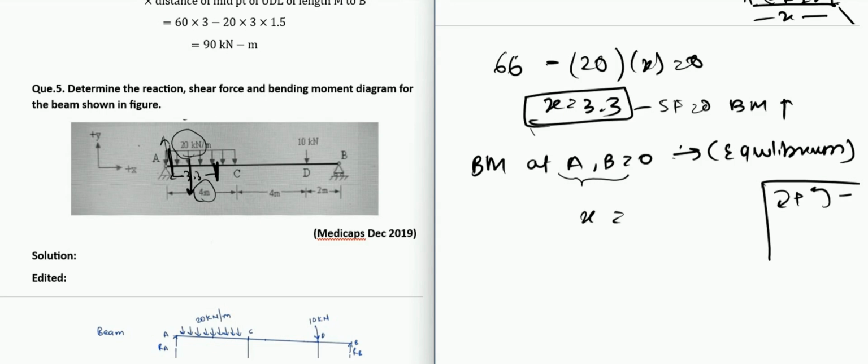And if you are calculating from the forces on the right, then you have to give clockwise as negative and anti-clockwise as positive. So just the opposite of this. You just need to remember that whenever you are calculating bending moment from the left side of the cross section, you give clockwise as positive and anti-clockwise as negative. That is what we are doing right now: calculating at some point x and considering forces on the left side, so we give clockwise as positive and anti-clockwise as negative.